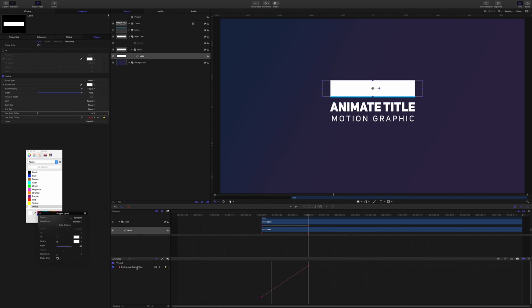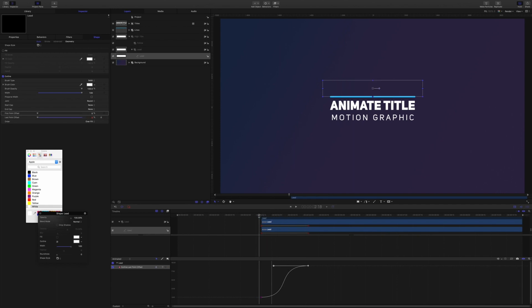And I'm going to come into the keyframe editor and grab that curve, set the interpolation to Bezier and break the tangents on the handles. So we're going to give this very hard ease in and ease out. Drag that handle that way and drag that handle this way. So we have a slow, stretched, slow animation, hopefully here.